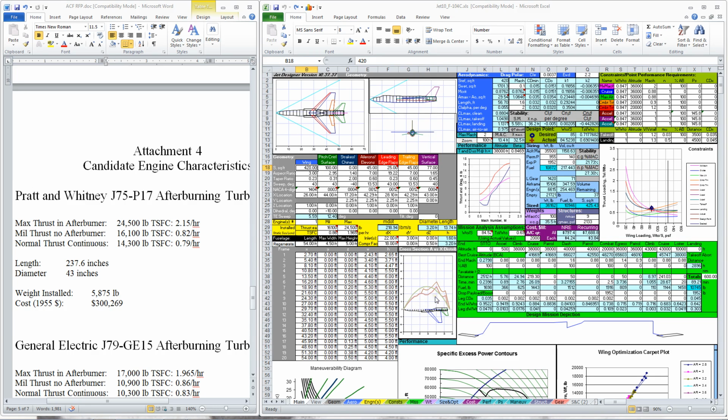One last look down here as we've moved our wing around. We've got a decent static margin. I don't want to mess with that. But our wing ended up a little further back, and so we have an issue with the A versus X. It's got kind of a peak right there, right at 40. And so we just want to make that 5.5 or something. Take the edge off of that, maybe even 5.